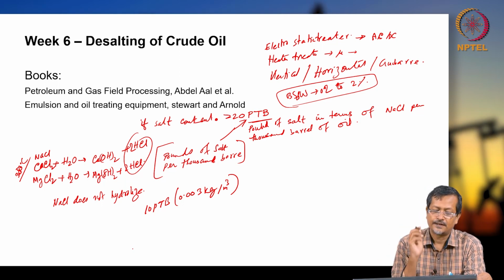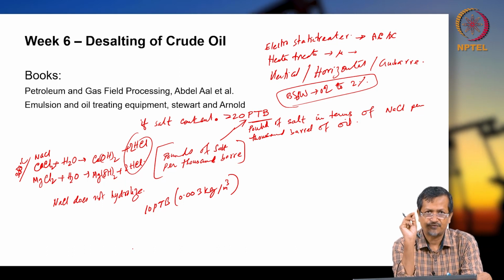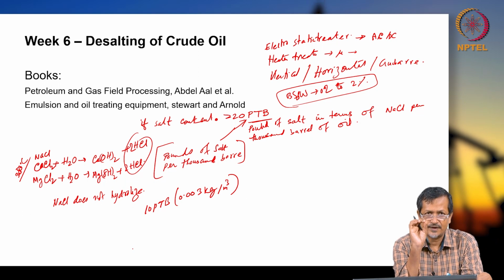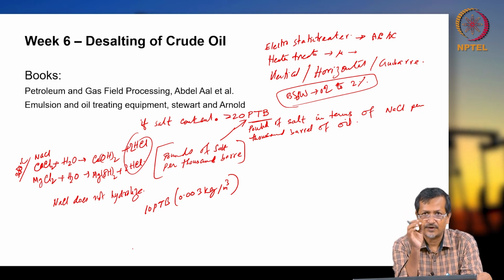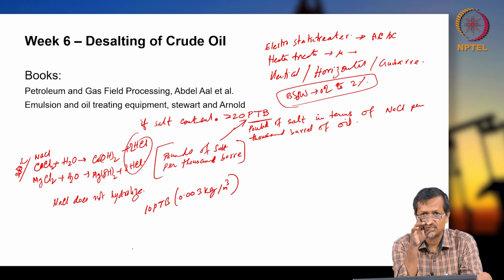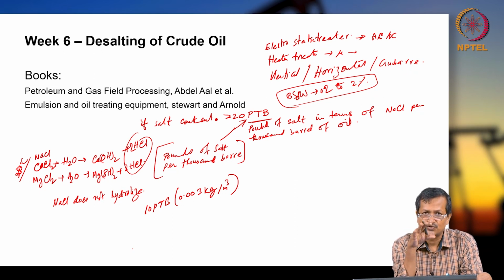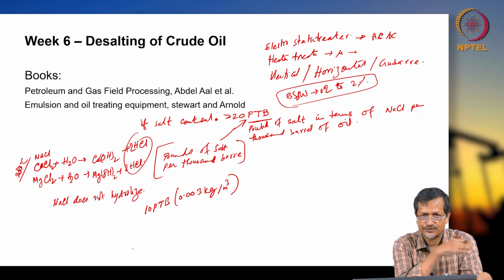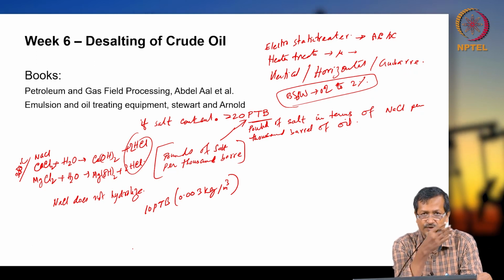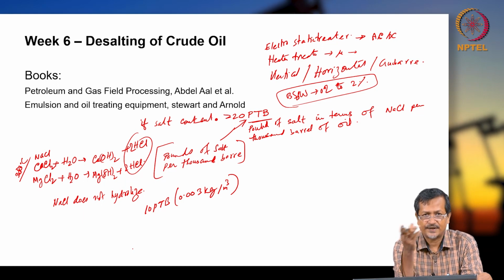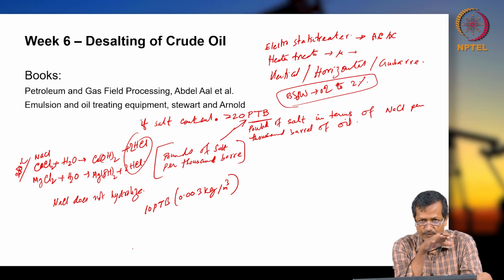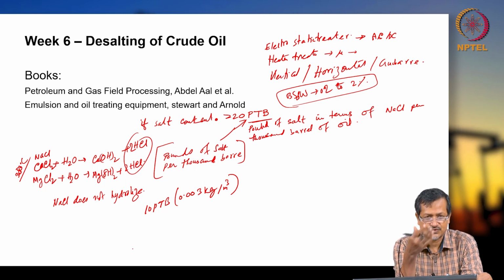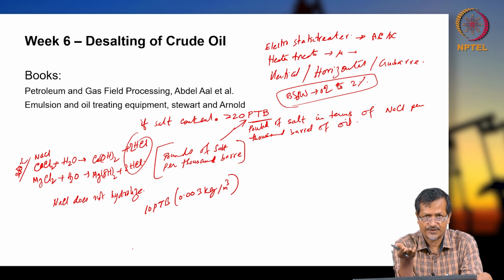Okay. So, whatever water you are using for washing, the criteria is that it should not have any H2S component, or it should not have any ammonia component, or your ppm, parts per million salt concentration or debris concentration should be lower. Otherwise, this salt whatever you are putting in as fresh water, the water for water washing, that water will be creating further problem. So, you have to remove all the salt, then use it for your water washing and remove your salt for desalting operation.